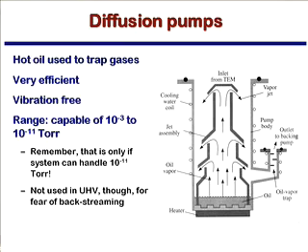In the case of the 2000 FX downstairs, that can cause some delay, because if you have a problem, it always goes through a 25-minute cycle where it heats, quote-unquote, heats the oil before initiating vacuum and opening it up to the machine, even if the oil is already hot. So if you have a short vacuum problem, right, you still have to wait that 25 minutes, and you cannot override it because they don't want you to have the ability to put the wrong pressure on that side of that thing and squirt it back up into the column, okay?